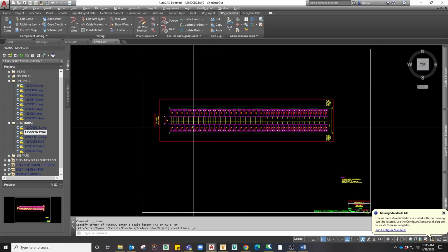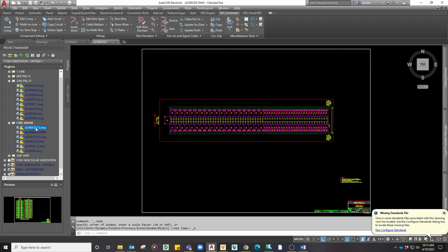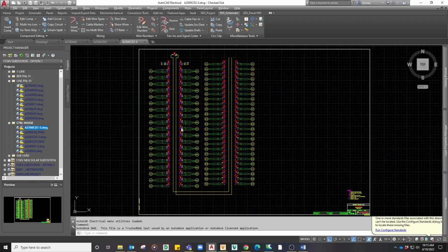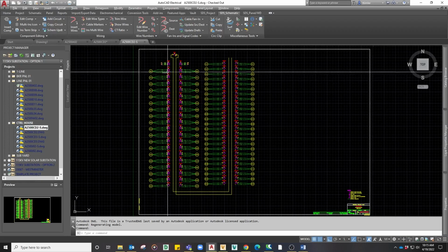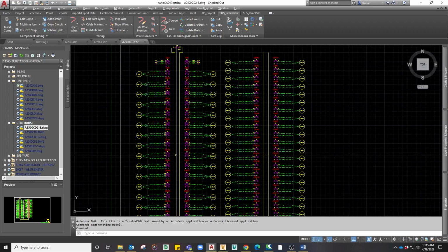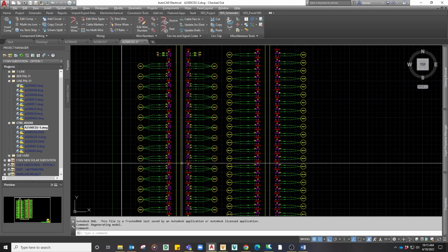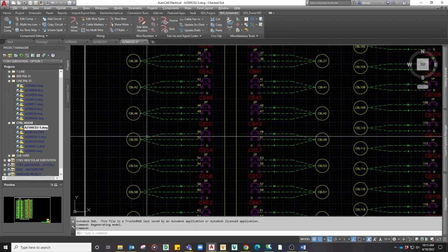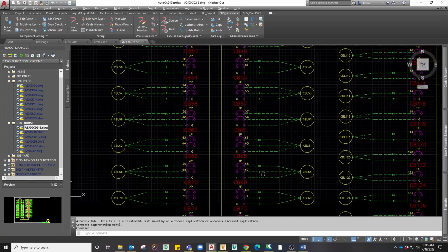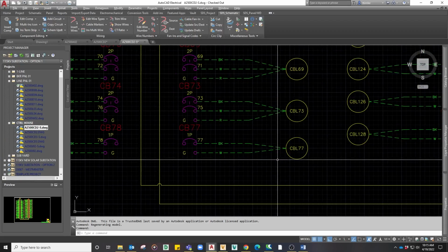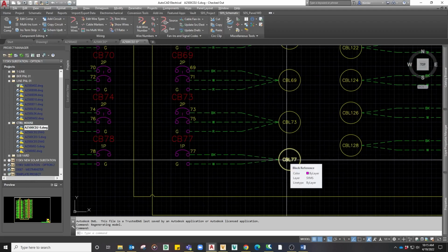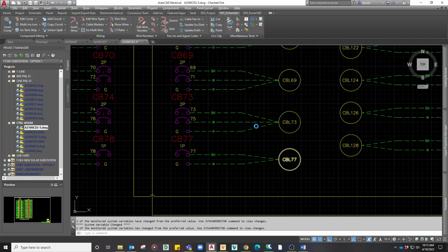Now, I'll go ahead and open up my supplemental AC distribution panel schematic and locate CB77. All breakers in this supplemental schematic have been pre-wired with child cables and destination signal arrows. All I have to do is change the default tag to whatever cable I want to match the cable tag coming from the parent side of the cable, and rerun SDS cable SIG fan update to match the destination signal codes to the new cable tag.